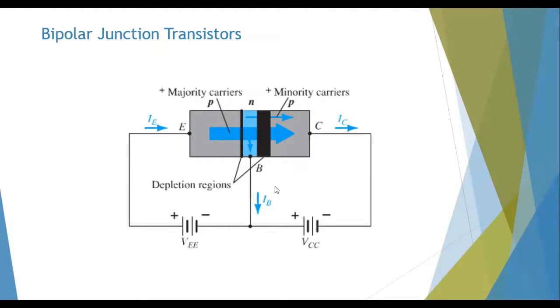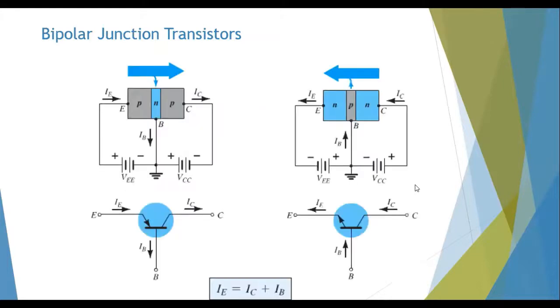Now, this diagram is interesting. It is also showing the currents. Yeah, because definitely you have a current. Now, the source of charge is always the emitter. And you see IE there is a current which is originating from the emitter. So in all transistors, the relationship always holds that IE, which is the main source current, is equal to IB plus IC. It's Kirchhoff's current law here. So IE is the emitter, the source of current, and this current IE is split into IB and IC. Yeah, so for PNP, for any transistor, you always have this relationship. That's a very important relationship.